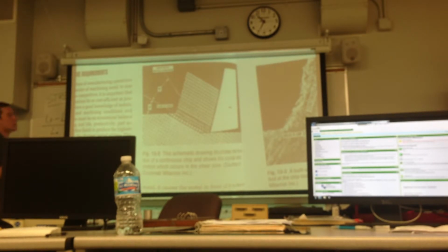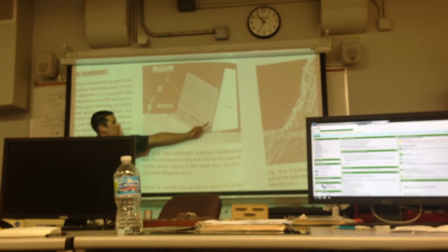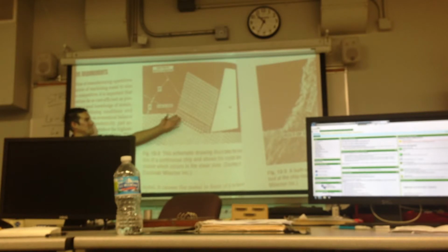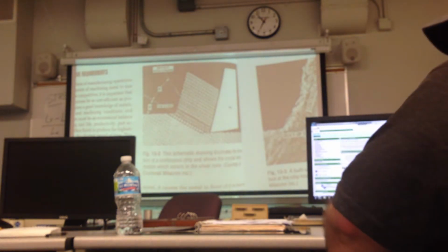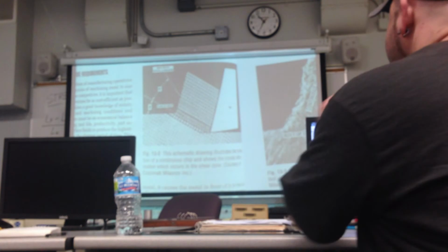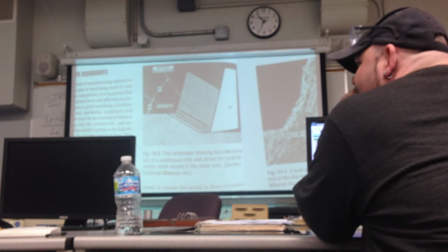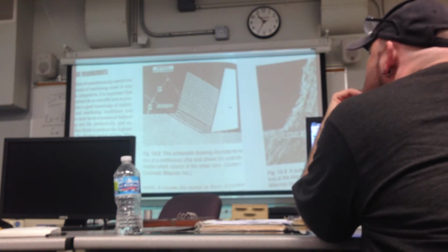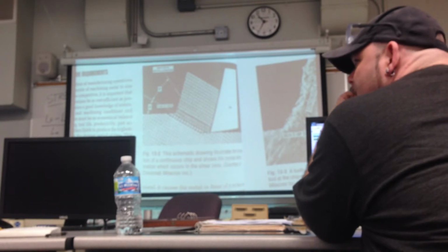Well, what you definitely need to know is that this shear plane is created by the tool, all right? And you can see this in the chip, actually. If you look at the chip, the back side and the front side, you'll see those grains elongated. They actually get kind of distorted after that. So the chips are very hard because of that. They're going to be a lot harder than the material because they've been cold worked. The lattice structure has been deformed like that.